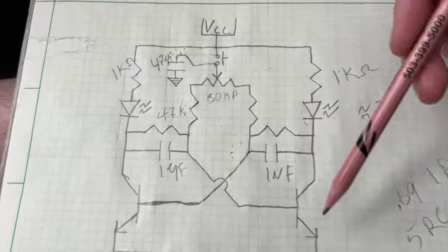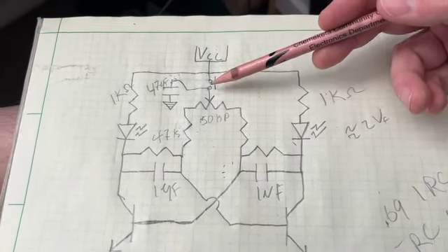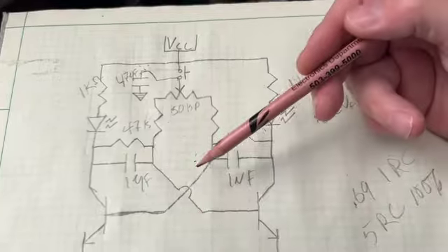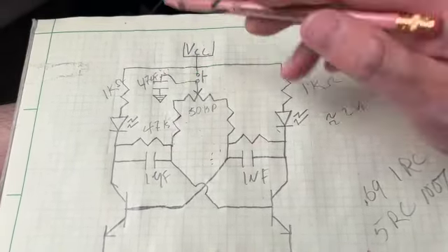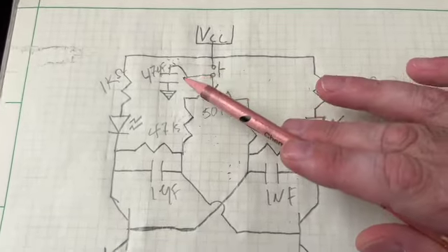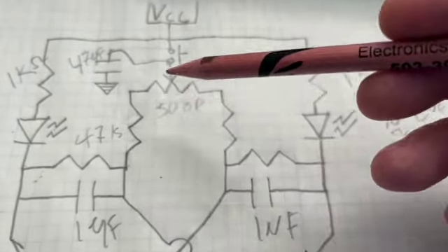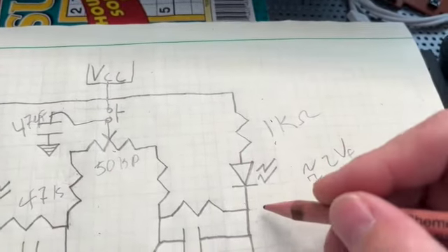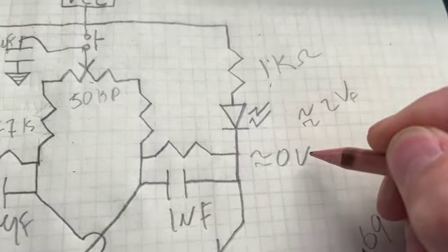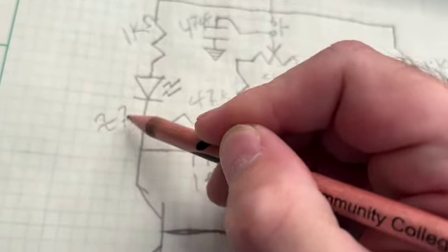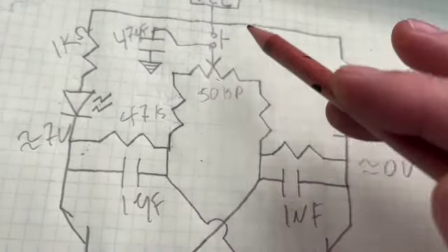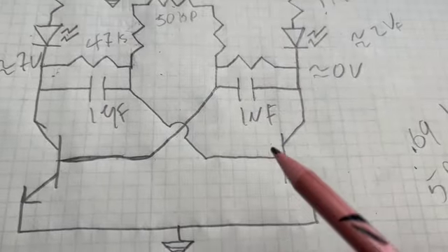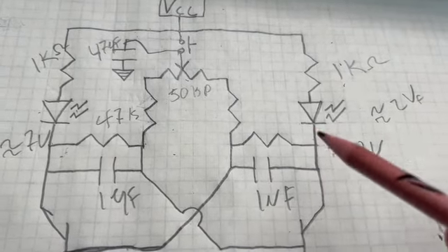If you're looking to recreate this circuit, all you got to understand is that you put this push button going into this potentiometer. When you press that down, it goes into the oscillation mode. Now, what's nice is when you let go and the capacitor discharges, which means that it's essentially got no charge there. So when you get no charge here, let's say this LED is on, this LED is off. So this is essentially 0 volts, and this is about 7 volts. Now, since there's no charge here, this 7 volts is going to take this path here, its quickest path to ground, to activate this LED here.